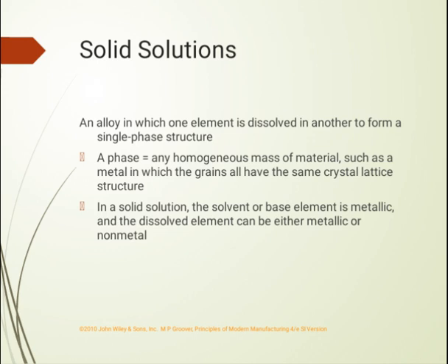Solid solution is a form of alloy where one element is dissolved in another to form a single phase structure. This single phase has a homogeneous mass of material, such as metal in which the grains all have the same crystal lattice structure.